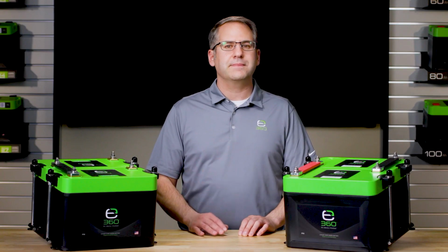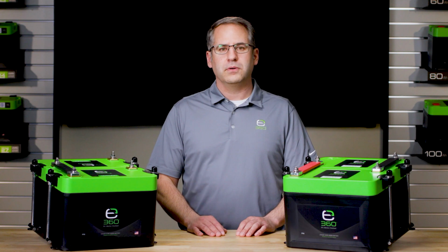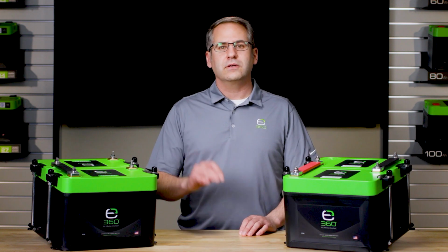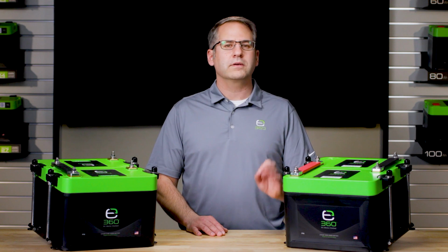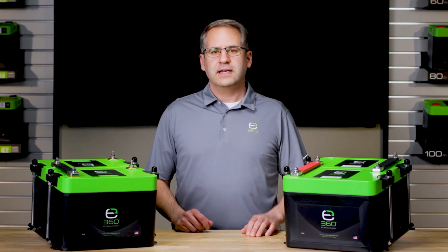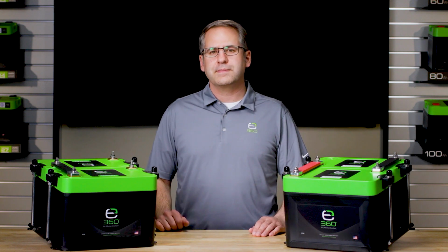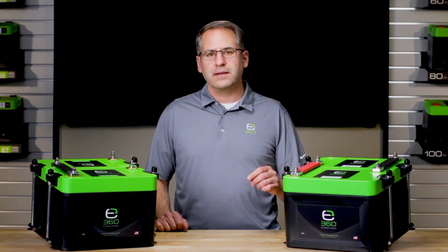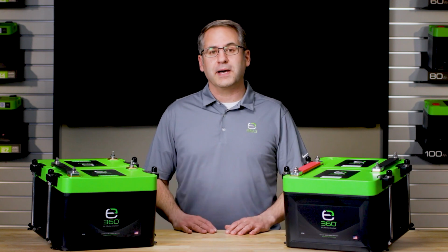When looking at RVs, it's probably more common to see breakers in AC loads and fuses for DC loads. There are basically 3 different types of circuit breakers. They are single pole, double pole, and ground fault. Single pole breakers are designed for small 120 volt AC circuits, while double pole breakers are used for larger 240 volt AC circuits that feed appliances like ovens and furnaces. A ground fault circuit breaker is a very sensitive device designed to prevent electrocution by interrupting the circuit when it detects a current imbalance due to power entering a human's body.